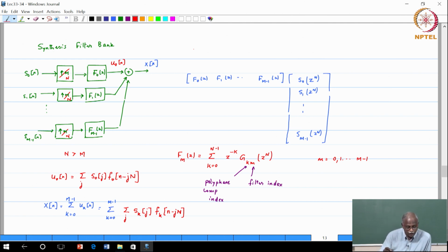So, this is a place where we can see that the different subcarriers are mixing, okay, because this x of n is actually a multicarrier signal. So, this is where the subcarriers are mixing, or in other words, the sub channels are mixing. So, we have to design our carriers in such a way that these mixing parts are taken care of correctly, and then we are able to recover the signal in a very effective manner.